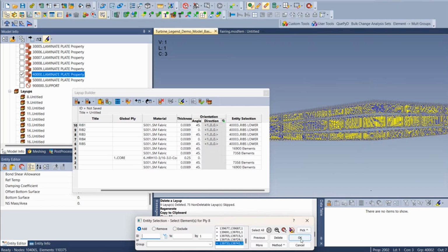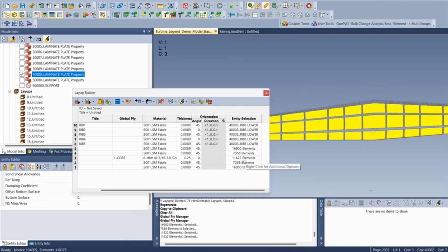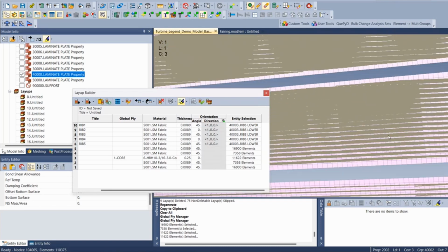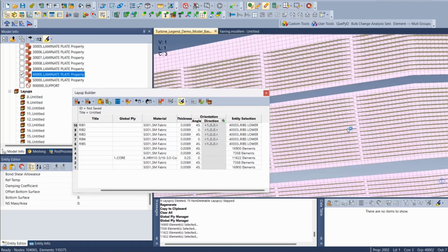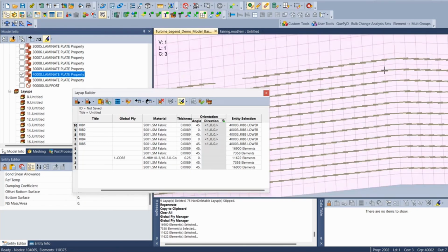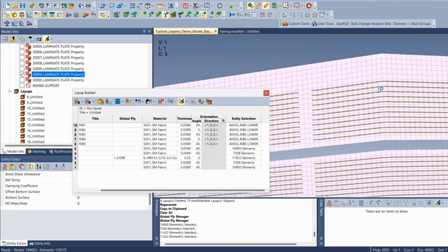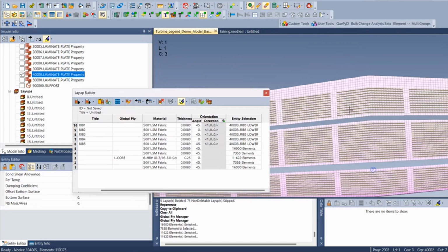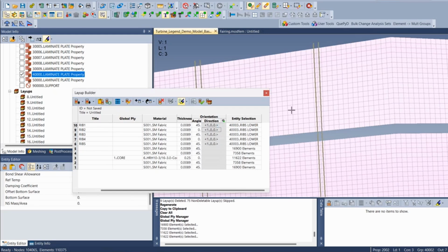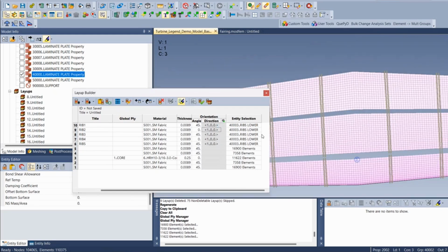Make sure that's set up. So if we click on the 0 direction of this ply here, I'm going to turn on ply fiber direction. You'll notice that the fiber direction is actually still 0 based off here. This is actually based off the defined material orientation of the model, which I think I may have reset at one point. I might have defined the material orientations along the wing here. But then here, you can see that this material orientation is lined up with X.